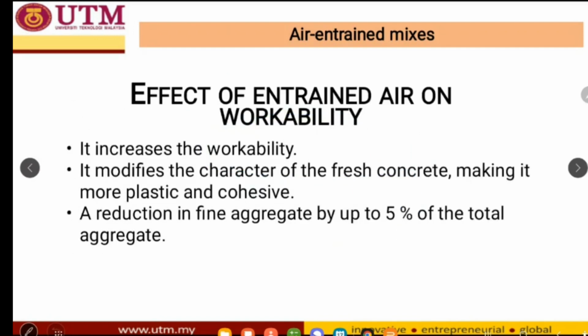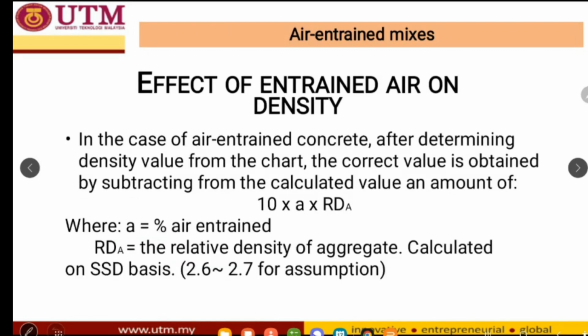So what are the effects of the entrained air on the workability? Aside from strength, it will slightly increase the workability, and it modifies the character of the fresh concrete, making it more plastic and cohesive. So a reduction in fine aggregate of up to 5% of the total aggregate is possible. This is the consideration that we will put into our mix design later on when we perform the mix design for the air-entrained concrete.